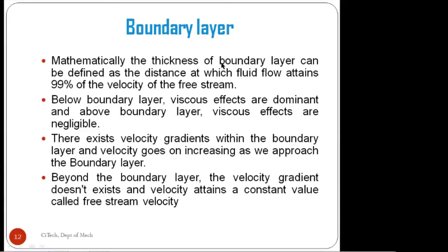Mathematically, the thickness of the boundary layer can be defined as the distance at which the fluid flow attains 99% of the free-stream velocity.